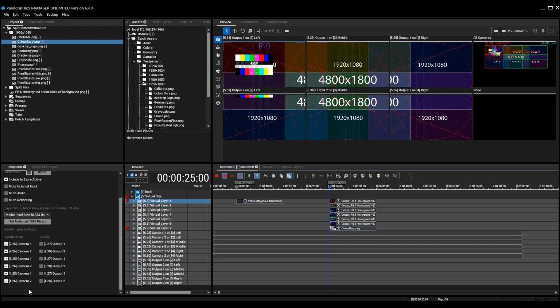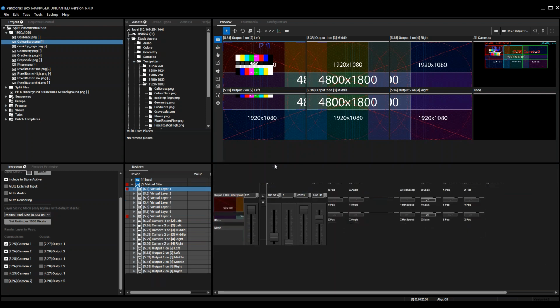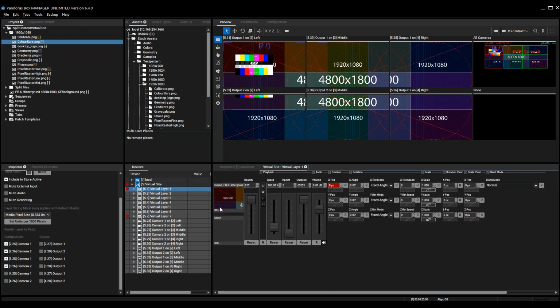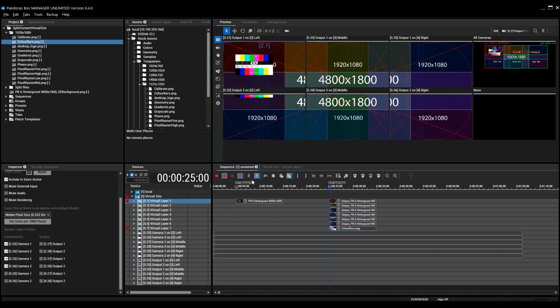I would say server number 1 does not need the content from server number 3. So for the first server, I deselect the last ones for the split content files. And therefore you would save performance again. So splitting content files, very nice, and route your content to a specific camera.